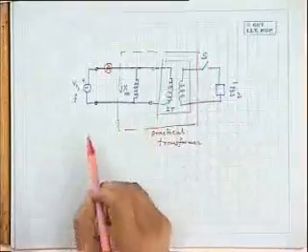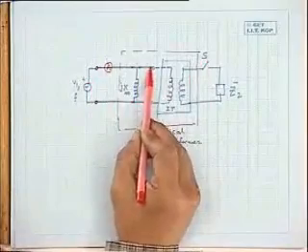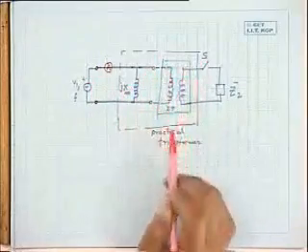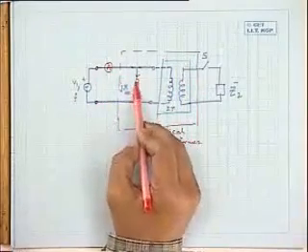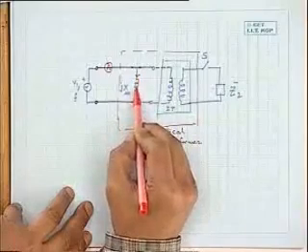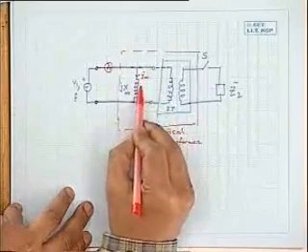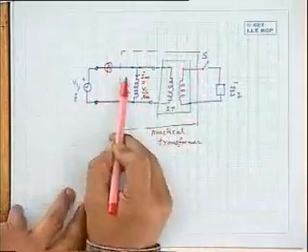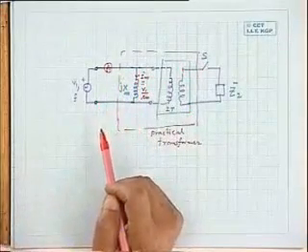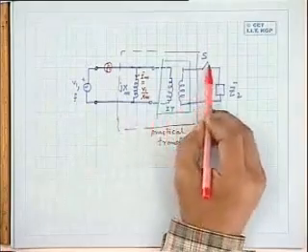Okay. Now let us see whether it satisfies my no load and loaded condition operation, whether I can explain them with this equivalent circuit or not. And here is an ammeter connected. With S opened, this is the supply voltage. How much current is drawn this side? 0, because this is an ideal transformer. That we have already seen. But this is not a transformer winding, this you must understand. This is some reactance I am representing to take care of IM. This current is your IM, which is equal to V1 by Xm, the magnitude of this current. So during no load condition, the ammeter will read only Im.